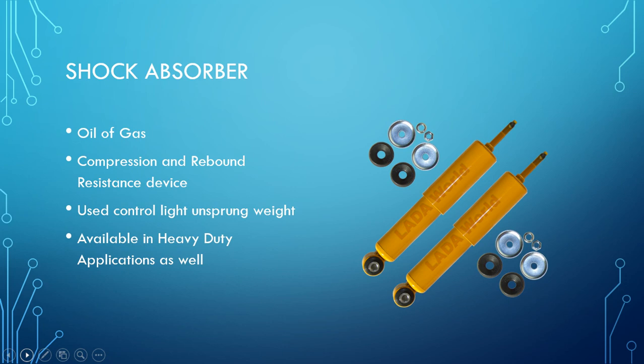Some of these shocks on light truck applications with rear tow loads can be upgraded to a tow package shock application. Something that needs to be noted when servicing these struts and shocks is what they are being used for on a daily basis, whether it's a commercial vehicle or a passenger vehicle. Those things need to be considered in choosing the correct strut or shock quality for the application.